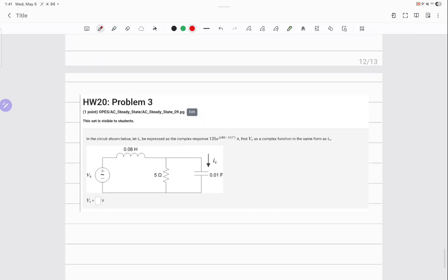Okay, so if I multiply IC by the impedance of this guy, ZC, let's call it, what do I get? I get the voltage at this node, right? Or the voltage between these two points. Do you agree with that? Now, let's call this voltage V. Let's call this V1. So you know how to find V1 right now, so far. So do you agree with that?